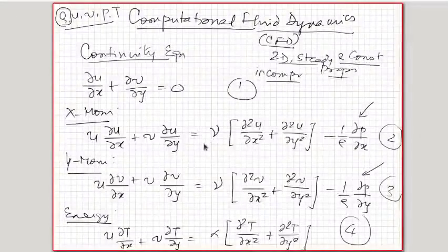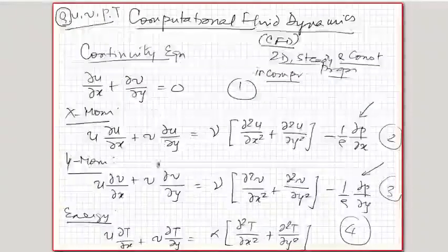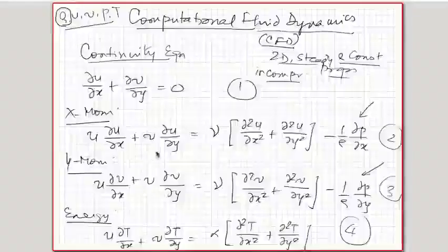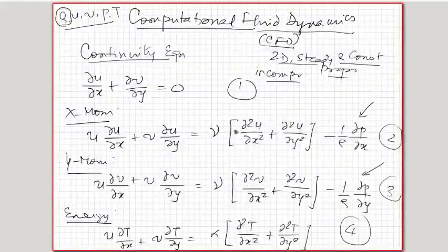It can be removed by elimination. In that process you transform these equations in terms of two other flow field variables called the stream function and vorticity. So one approach is the stream function vorticity approach, by which you eliminate pressure between these two equations using the continuity equation.